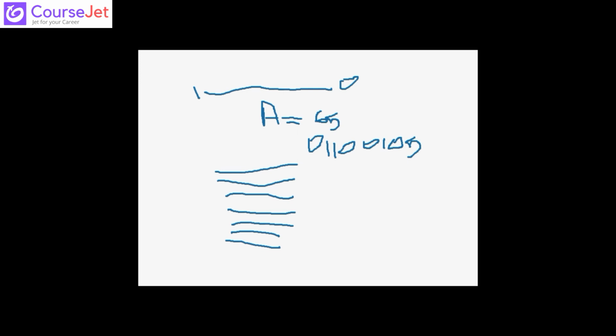So when you are going for serial communication, if you want to send 7 characters, it will take 56 machine cycles. But when you go for parallel communication, for 8 characters, it will take 8 machine cycles. That means here the thing is speed. 56 machine cycles is taking more time when compared to 8 machine cycles. So speed is a matter, but along with speed comes cost.